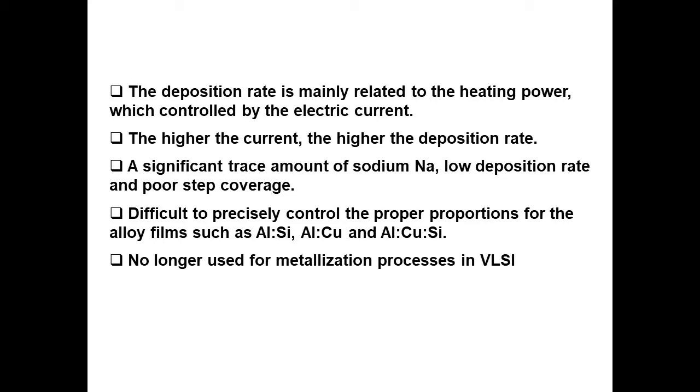Slide 67 tells us how you are going to control the deposition rate, and also the disadvantages of using the system. How are you going to control the deposition rate? It is related to the heating power, and this is controlled by the electric current. So if the current is high, then the deposition rate will be high.